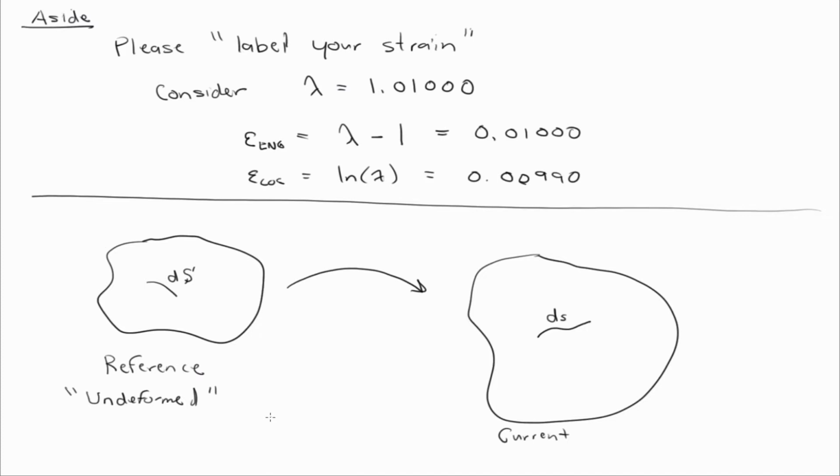Of course, in a geomechanical setting, if you're talking about parts of the earth at reservoir depths, they've clearly been deformed by tectonic stresses over time. So when we talk about the reference configuration, we're talking about the time t equals 0, where we make the decision what time t equals 0 is. So at some point we say, okay, we're going to start tracking the deformation from here. This is the reference configuration.